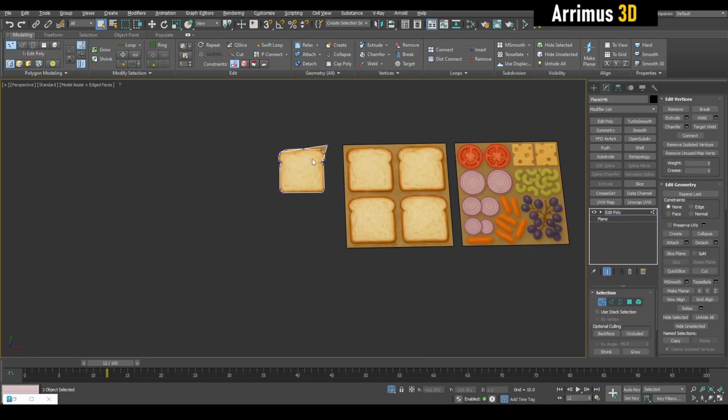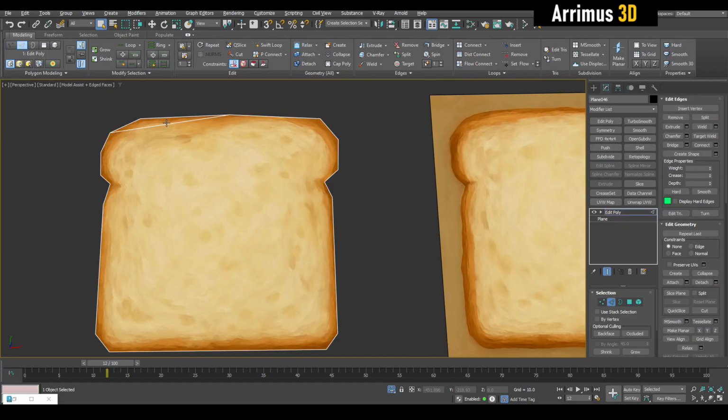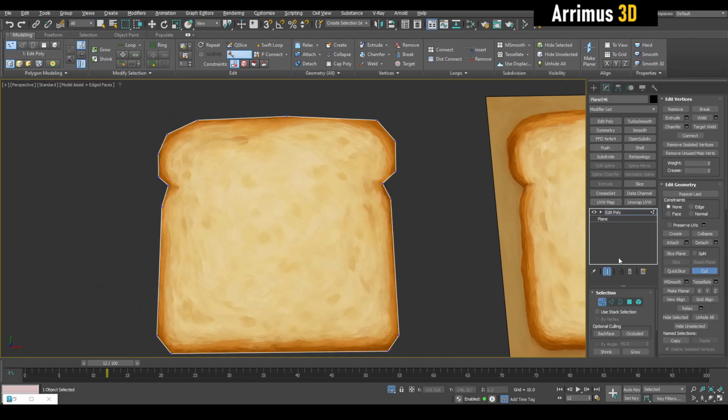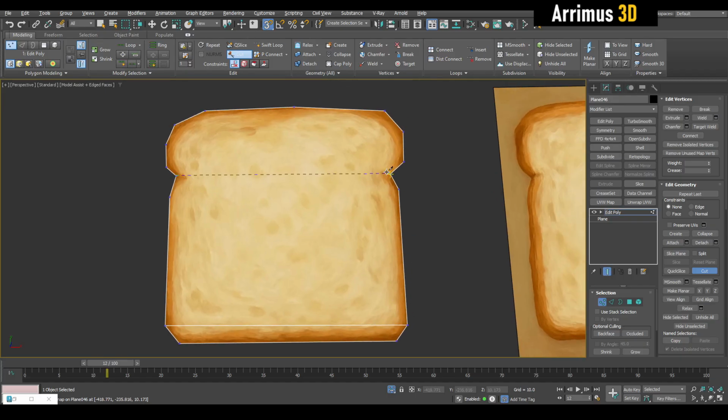All right, I'll just go ahead and delete everything else here. I can just maybe remove that. Now I'm going to cut. I'm going to press S for snaps, right click here, make sure you've got vertex snap on. I'm going to go from left to right, or right to left, and kind of make sure we have some clean topology going on here. We'll go like that as well. We're going to triangle here, that's fine.